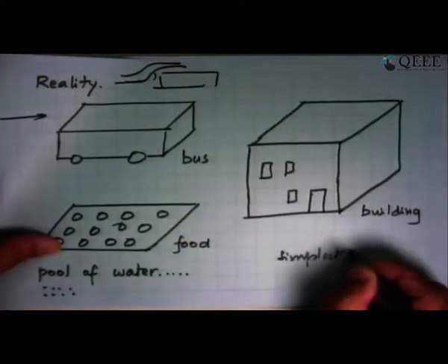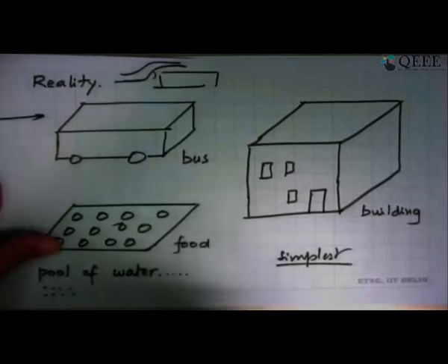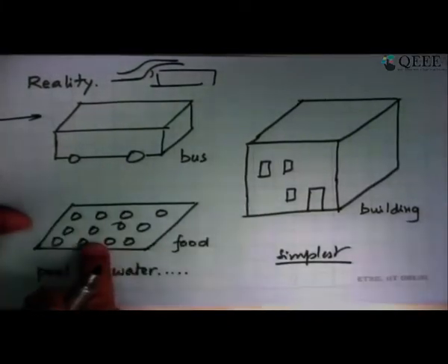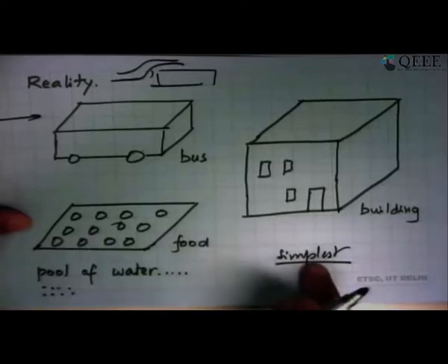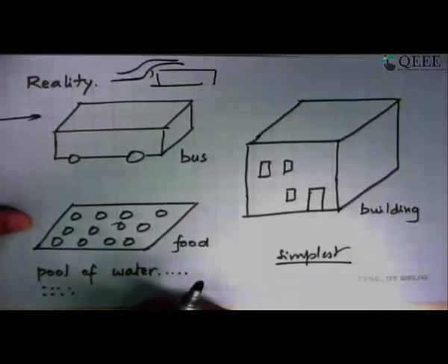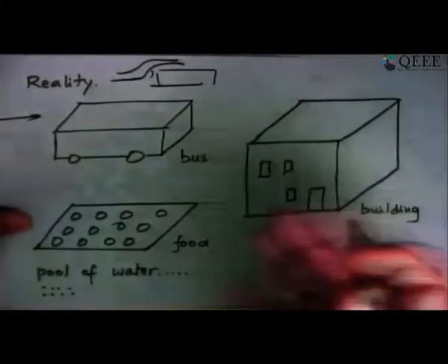So that's how we take a practical problem and reduce it to the simplest possible case, and that is always the nice thing to do whenever you solve even a complicated problem. If tomorrow you want to do a computational fluid dynamics or a computational heat transfer solution of this problem, it is good to do this simple analysis so you know where the answer is likely to come from. What is the order of magnitude? If your simulation is giving you something very different, you know there's something to worry about. I need to go back and read it.